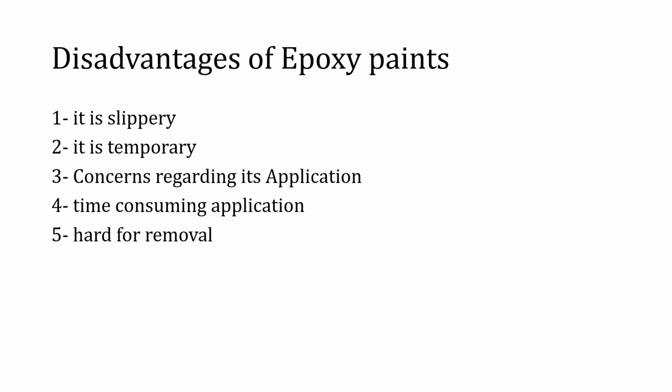Its removal could also be an issue. It can be costly and labor-intensive to change the color, design, or to have epoxy removed. Compared to epoxy coatings, the low solid content within the paint results in a much thinner protective layer. It means that it won't last nearly as long as an epoxy coating, and it isn't as resistant to chemicals as the other one. In other words, while it is more durable than traditional latex paint, it doesn't hold up to stains, chemicals, or abrasions very well.